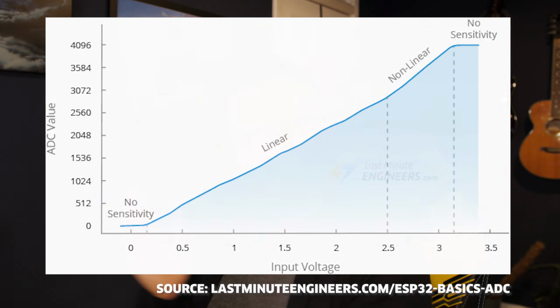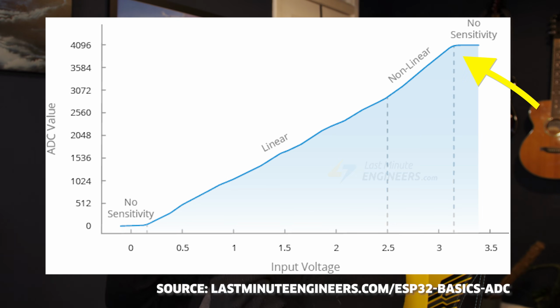So we need to convert the voltage from a maximum of 5 down to a maximum of 3.2, because in the way that ADC pins work, if you look at the data sheets for ESP32s, they read a nice pretty linear conversion from 1 through to 3.2, and then 3.2 to 3.3, it flattens out. It doesn't recognize the difference at the top end.